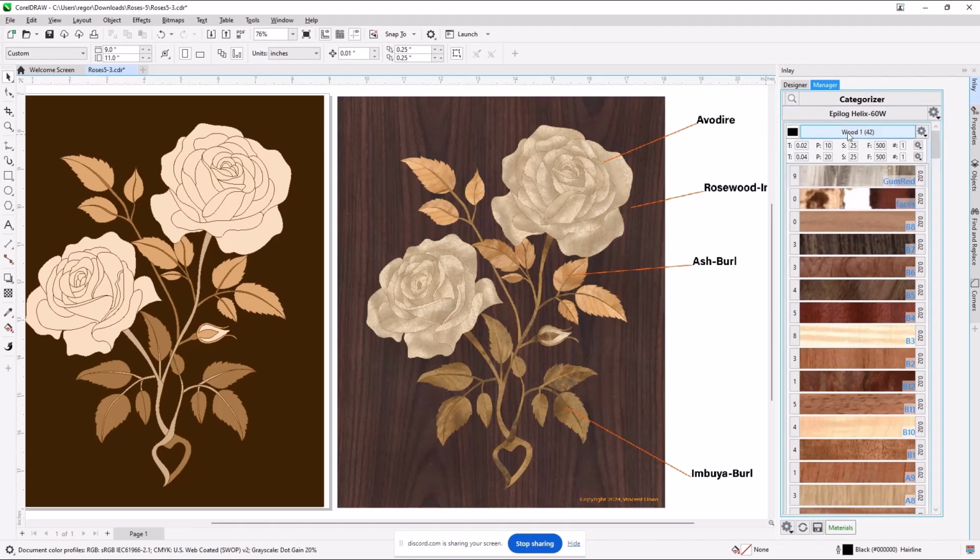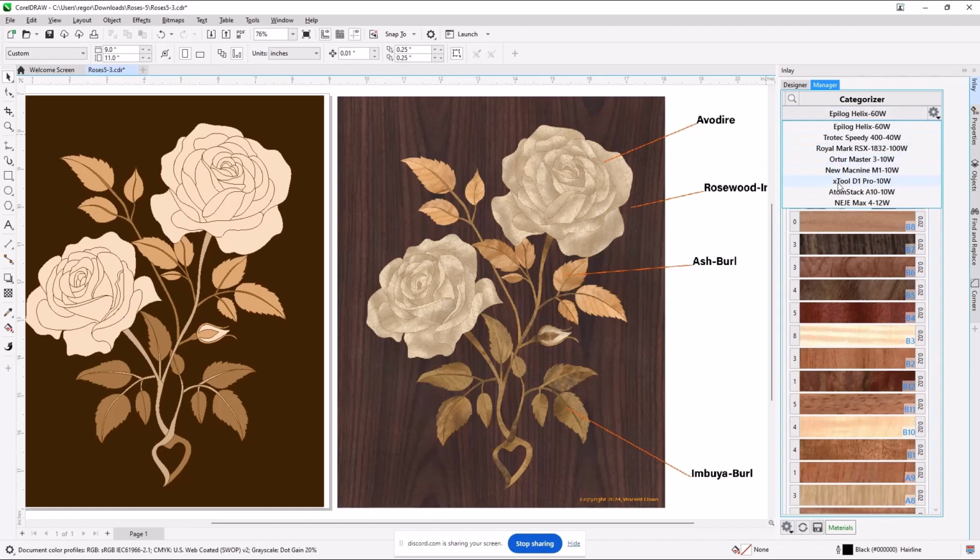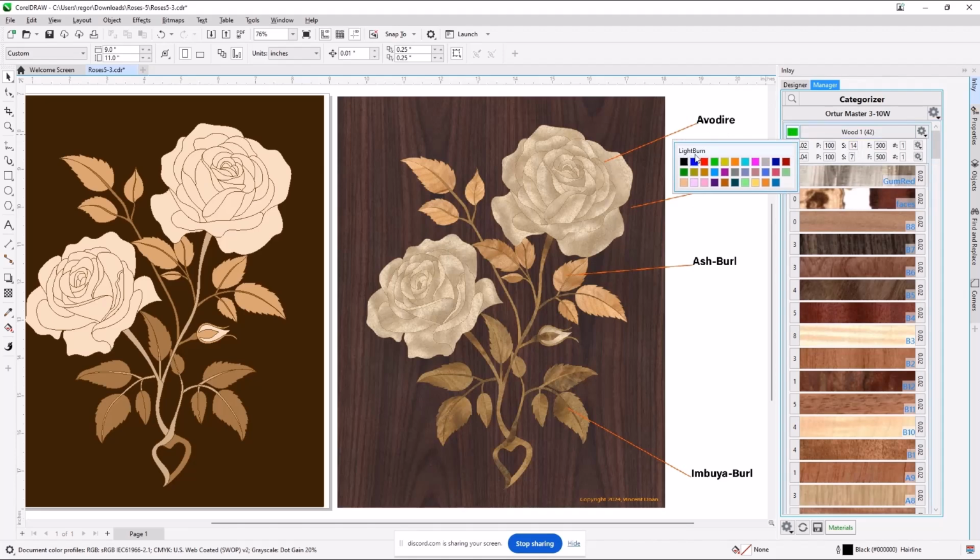So there's a color palette. In my case, the Epilog, if you look at the palette, has the ability to change the cut speed and a bunch of other things just on the basis of what color is the outline. So red or black, and I can go in and change under a color mapping scheme. I don't believe that's the case, but I do know that the ones that are set up for Lightburn have a separate color library, and I believe, correct me on this one, Travis, the last two colors are reserved for comments, and then you can specify all of the vector or other information you need for that color to be consistent with what you are doing in Lightburn.